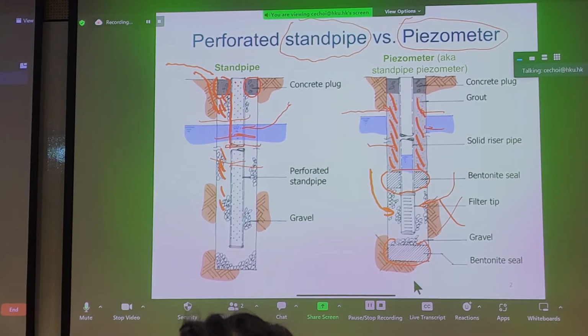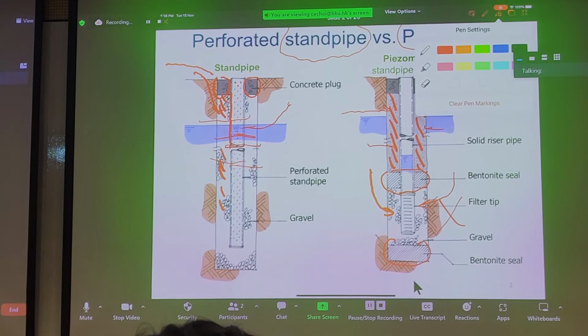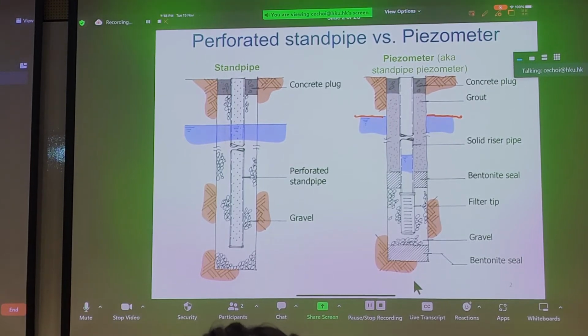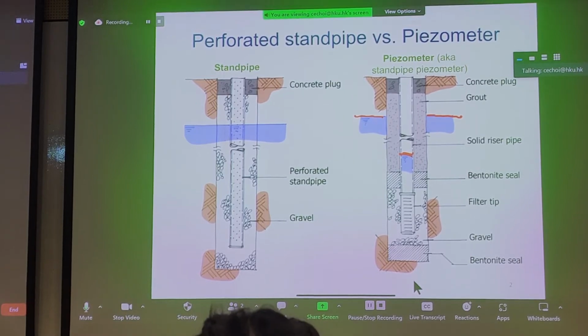If you look at the surface of the groundwater table here, outside the piezometer, you can see that it's quite different than that deduced inside the piezometer. It can be lower, right? It can also be higher. It depends on how groundwater is moving. Is it moving away or towards, right? We'll look at these examples later on.